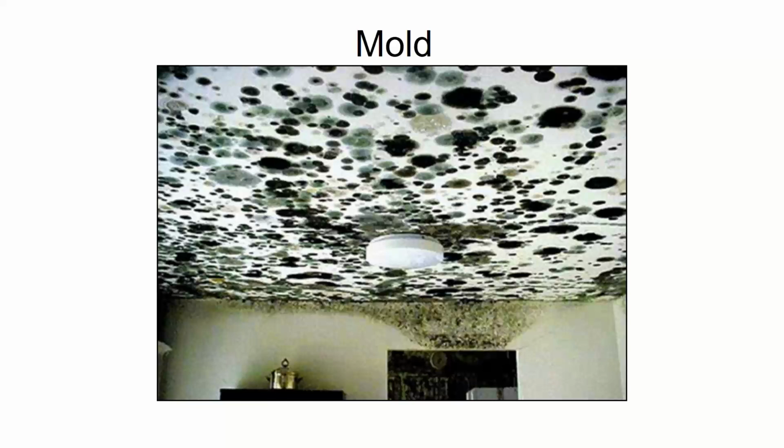So you have to have the mold spores, you have to have a food source. Both of those are very difficult to get rid of. And then you have to have a source of water for them. That's the one we're going to focus on because water, believe it or not, is the easiest of those 3 to get rid of. So if you get rid of all the water, then the other ones don't even matter.